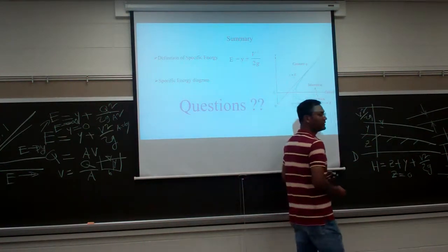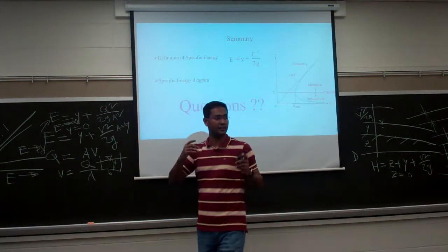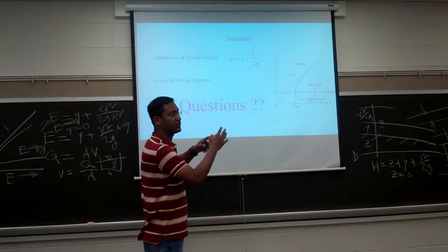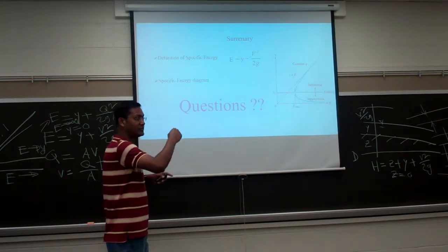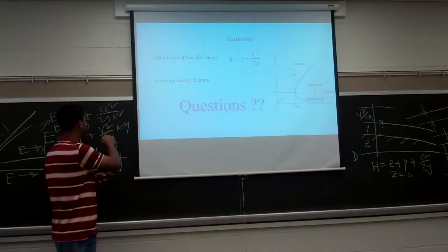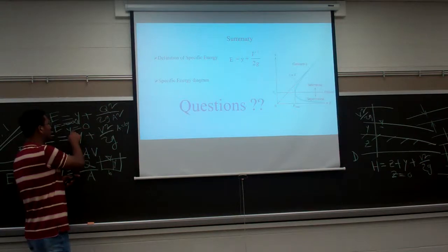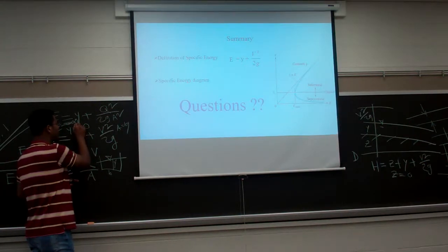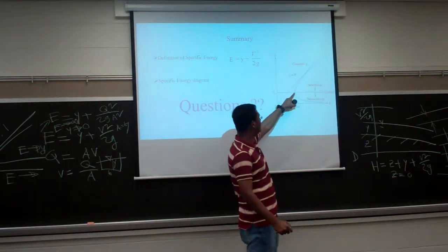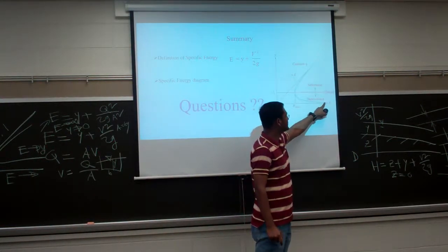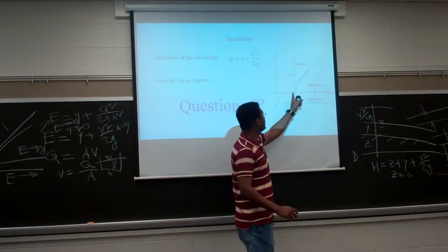See? When y equals 0 it means there is no water. So I am just drawing the curve as a qualitative diagram, not quantitative. So I am just assuming the lowest value of y. So what will happen if y is less than 0? I am not assuming that. I am assuming when y approaches 0, or y tends to 0. Then the curve will be like this. It will start from here and follow this curve. Right? And when the depth will be infinity, the line will be this.